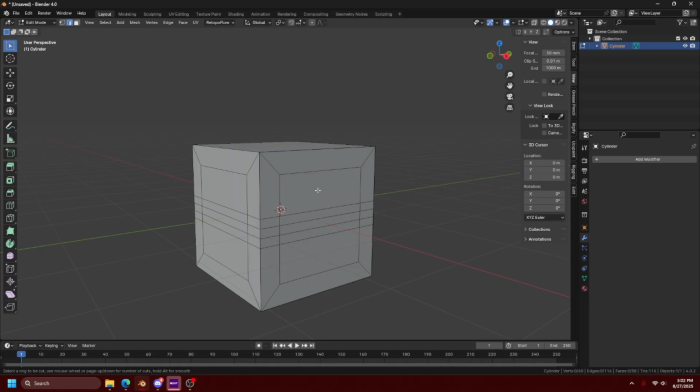If I'm selecting here, it doesn't know where I'm even selecting because I'm not anywhere near any edges. But if I want to cut vertically, I go to this edge because that's perpendicular vertically. If I want to cut horizontally, I go to this edge because that's horizontal. And that is how the loop cut decides where to highlight and give you where the loop is.